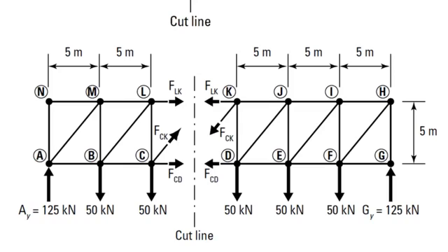We can see that for LK you either look at the right segment of the truss or the left. So if we look at the left, we have a force LK and we assume it's in tension, and we have a force CK and we assume again it's in tension, and force CD, and we always assume it's in tension just to keep our sign convention consistent.